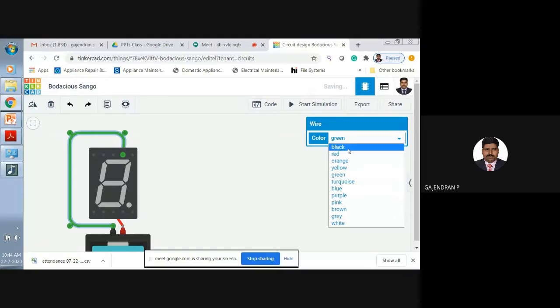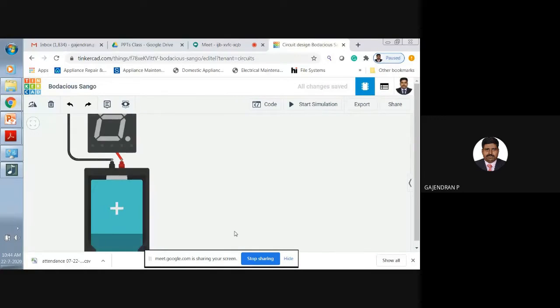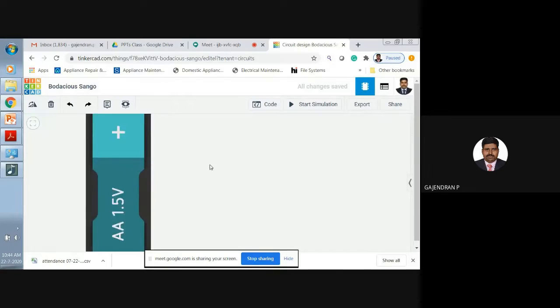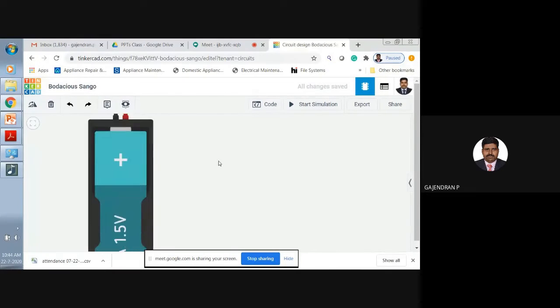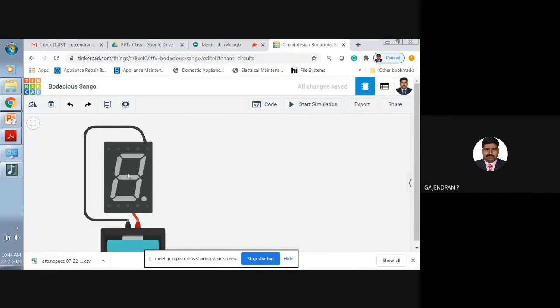Now I am going to change it to B and check. Yes, B is also working. In this fashion, you can check the 7-segment display with the help of a simple test voltage. If you have any LED, you can simply connect it, because it won't give much current. It won't damage your 7-segment display. Without any current limiting resistor, you can test it.